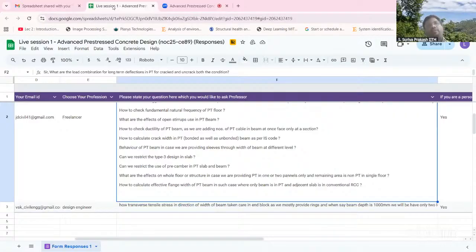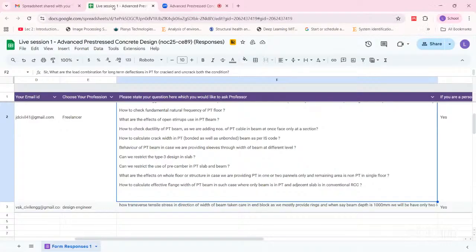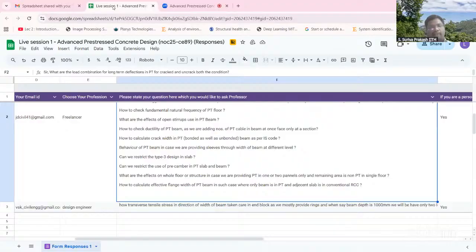You see, fundamentally, why do we go for post-tensioning or pre-stressing? Mainly from a serviceability point of view. So whichever panels you have, larger panels, or maybe you are expecting large live loads, that can be done individually with PT. We have no problem, but coordinating and doing it, you have to do it carefully. Maybe the other areas have shorter spans, so probably to economize the cost, they go for RC.